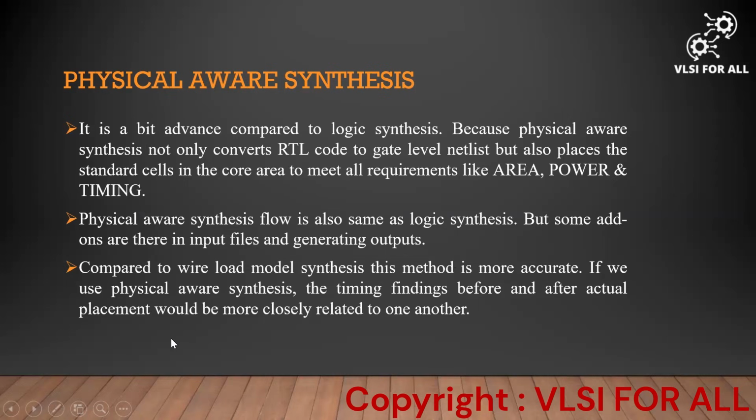So now, compared to logic synthesis, there we have the wire load model synthesis. This method is more accurate, where we are using physical aware synthesis. If you use physical aware synthesis, the timing of before and after actual placement would be more closely related to one another, which means the major issue which we face is fixing the timing, area utilization, and power. So these are all the major concerns for a chip design. In physical aware synthesis, it is very accurate to determine all these things and it is easy to fix them. We'll discuss the physical aware synthesis flow also.